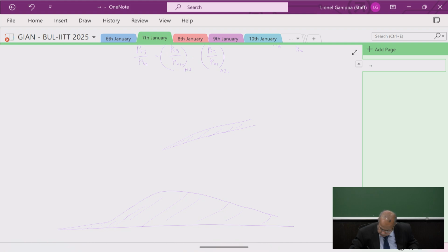So there is a leading edge here, the spike, which holds this oblique shock 1, which causes the flow coming in at M1 to turn exactly by the angle theta 1. So it turns. But then this flow will hit this convergent part of it. So the second oblique shock is initiated from the concave surface of the second part of the compression ramp. So this is oblique shock 2.